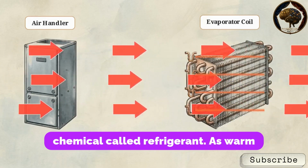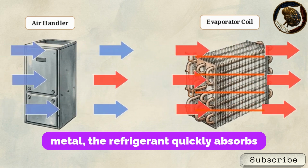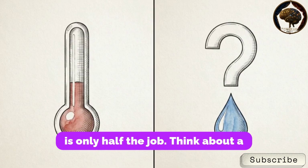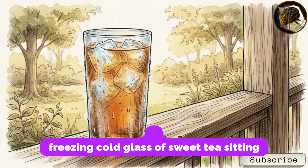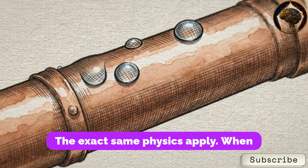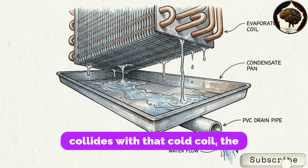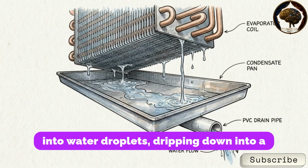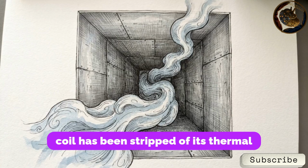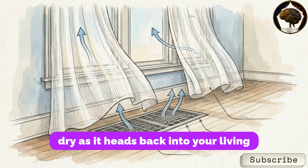Inside is a specialized chemical called refrigerant. As warm indoor air is forced over the freezing metal, the refrigerant quickly absorbs the thermal energy. But removing the heat is only half the job. Think about a freezing cold glass of sweet tea sitting on a porch in the middle of summer. The exact same physics apply here. When the warm, humid air from your home collides with that cold coil, the moisture in the air rapidly condenses into water droplets, dripping down into a pan to be drained away. Air exiting this coil has been stripped of its thermal weight and humidity, leaving it crisp and dry as it heads back into your living space.